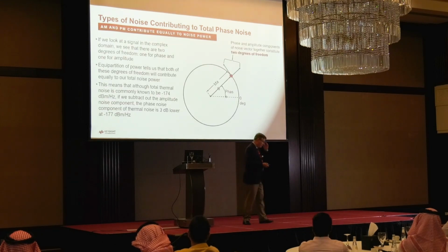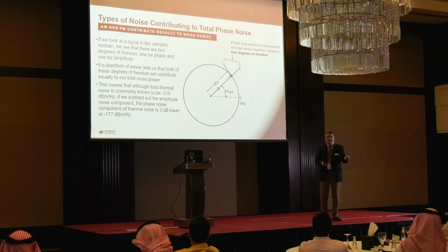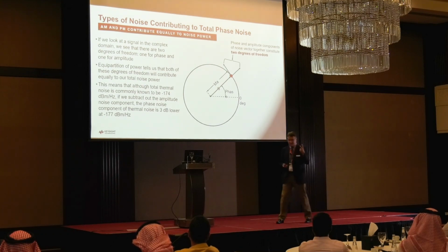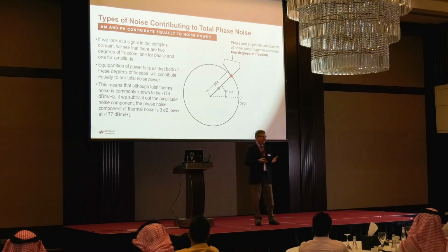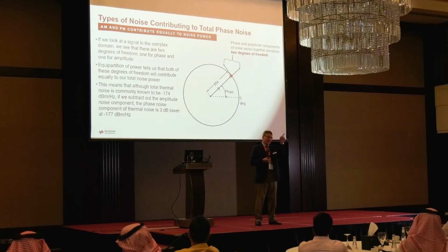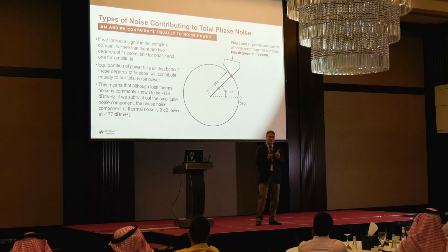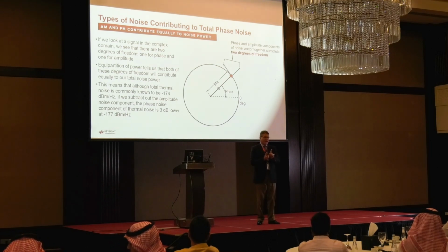Now, if we talk about phase noise, there's an interesting fact here: in the phase noise world, we actually see that there are two types of modulations that are affecting the amplitude of my carrier of interest. There is some phase modulation and there is some amplitude modulation. So back to our phasor diagram, you have this situation of two sources of noise, an AM noise component and a phase noise component. We don't care about the AM noise. We want to measure phase noise, just these instantaneous deviations in phase of my carrier frequency.